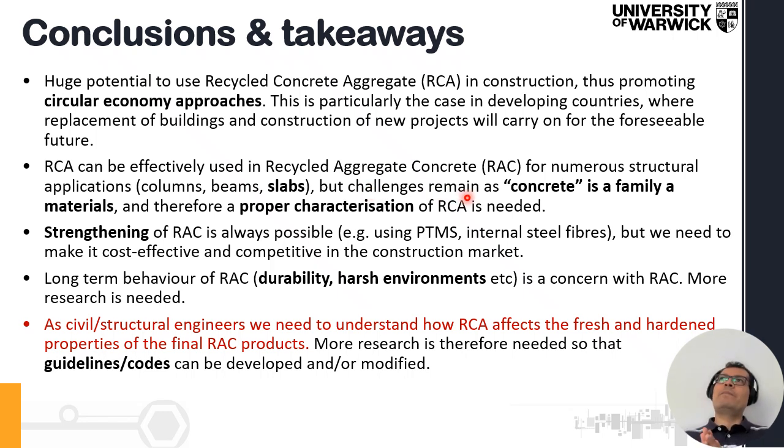But of course, we need to keep in mind that concrete is not a material, it's a big family of materials. And therefore, we need to understand and characterize the recycled concrete aggregate before we use it. So we need to know how much water it absorbs, abrasion, density, and so on, so that we can know the effects both on the fresh and the hardened properties of the new RAC.